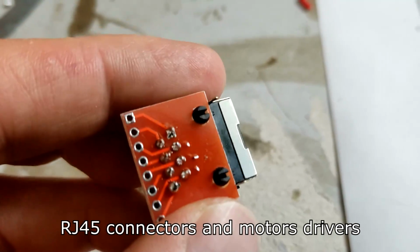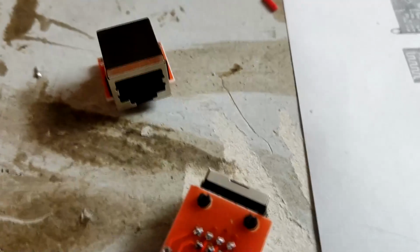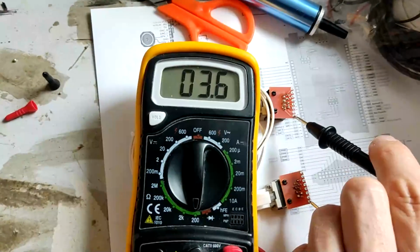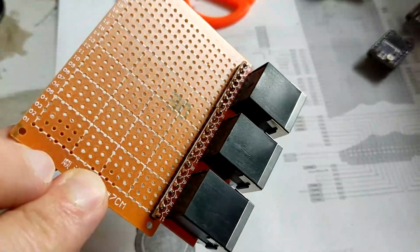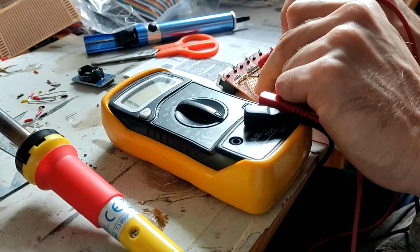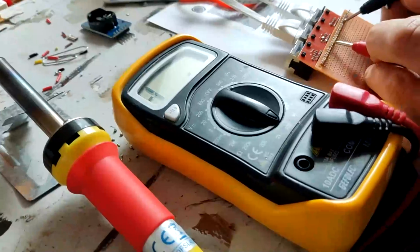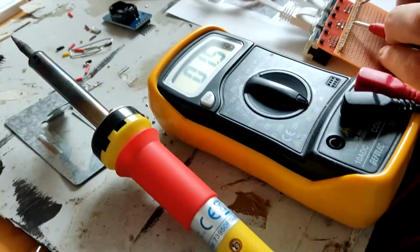I soldered the mini PCB on the RJ45 connector, then I tested it with a cable plugged in it and a multimeter in on position to see if the current is passing through. Then I soldered the 3 connectors on a universal PCB. The 5 by 7 cm was just the right size. Then I tested the solders to find if there were any bridges, the same method as seen before, with a multimeter in on position. And the same thing with the cable plugged in the connector 2x2 to see if the current is passing through.